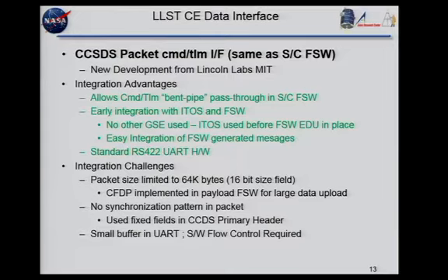One of the things I didn't mention, the synchronization, when we're using CCSDS, was that we're using packets coming over a serial wire. There's no sync pattern to sync on. If you start at the beginning and you get every byte, everything's good because you have a length field. You know where the next packet's going to be based on how large that packet is. But if you get off by a byte, then you're hosed for the rest of the time because you'll never find it again.